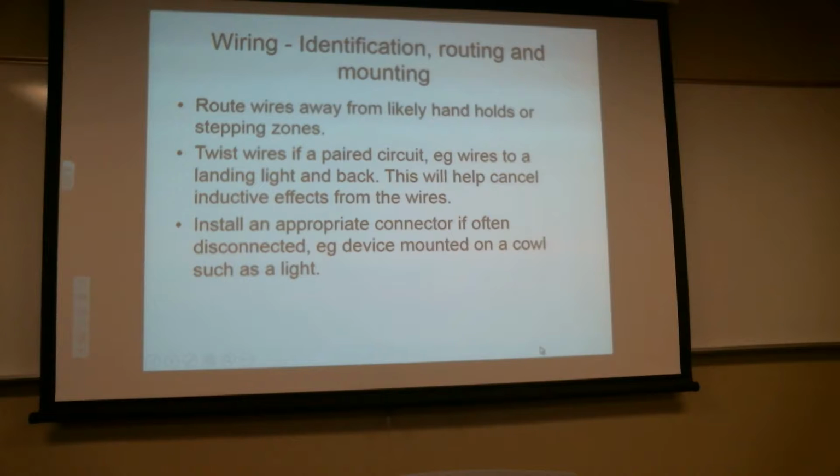Now, I do concur with the general practice of not running grounds back through the airframe. Again, there are many cases where it's hard not to, but I just have seen so many ground loop problems over the years that grounding the chassis is not always the best way to go. Does add some more weight though.